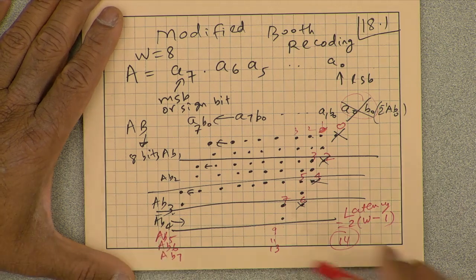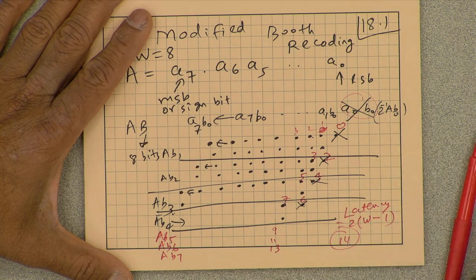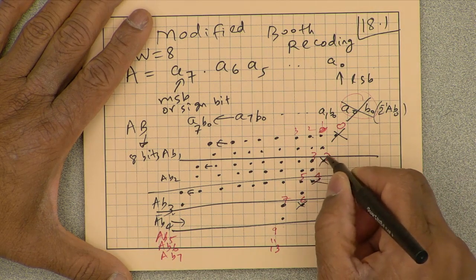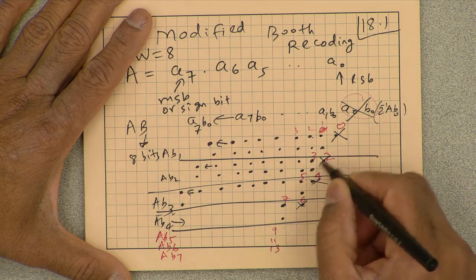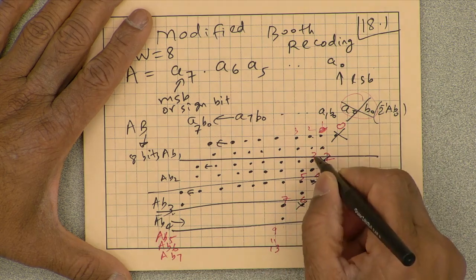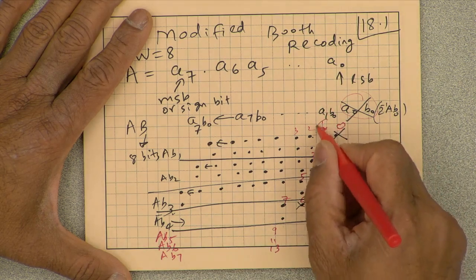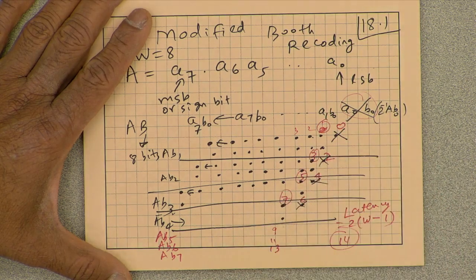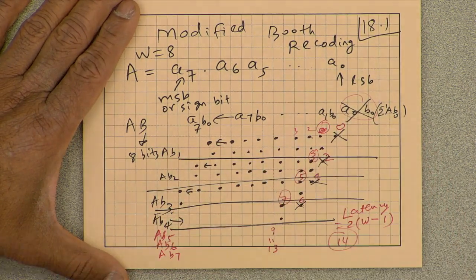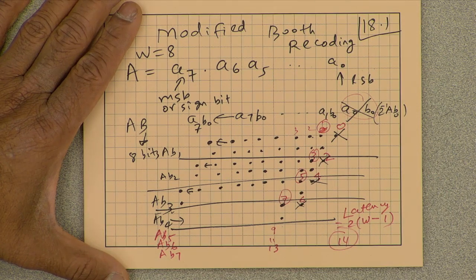Out of these 14 cycles, as you notice here, these positions either start with the neglected bits or eliminated bits 2, 4, 6, 8, etc. Or you think about the first add positions, which are 1, 3, 5, 7, etc. So every time I have a new row to add, that introduces a latency of 2 cycles.